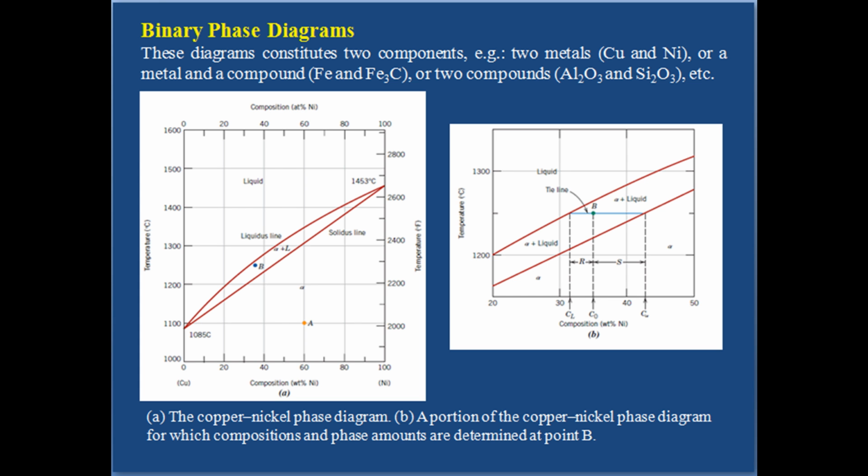In systems other than isomorphous systems, that is, in the case of limited solid solubility, there exist solid-state miscibility gaps. A number of invariant reactions can take place. Intermediate phases may exist over a range of compositions. These intermediate phases may undergo polymorphic transformation and some may melt at a fixed temperature.